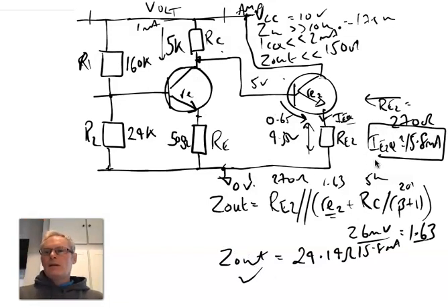Now we can see that the IEQ, because this is constantly biased, is going to well exceed our specifications in terms of quiescent draw as a system as a whole. However, what we've demonstrated is we can break the system up into stages.